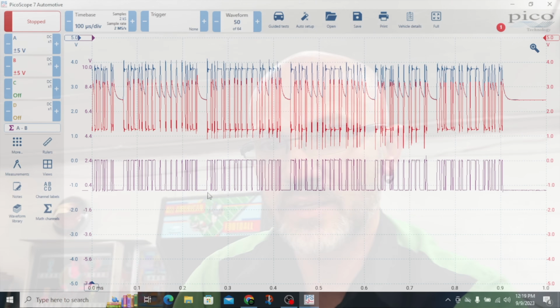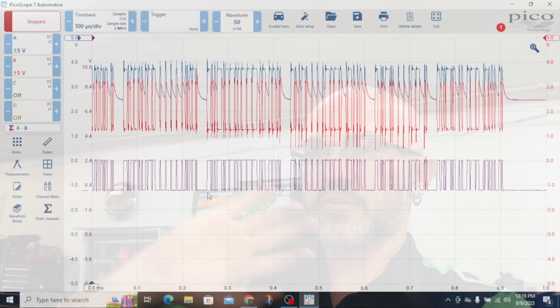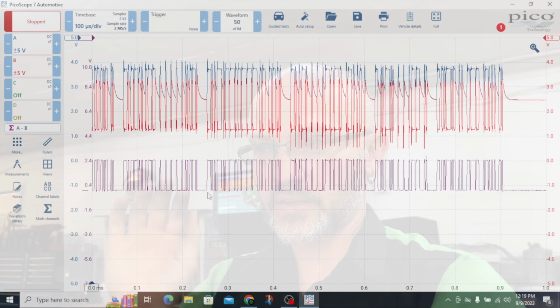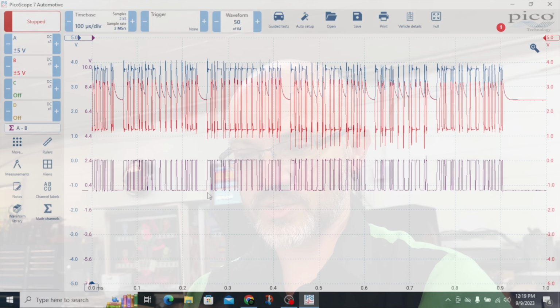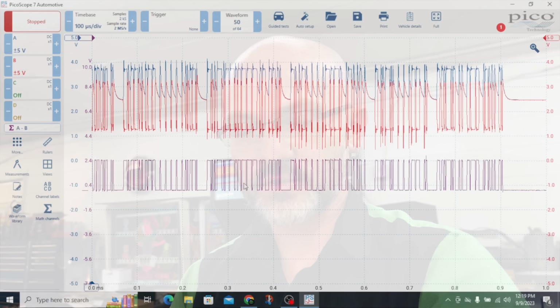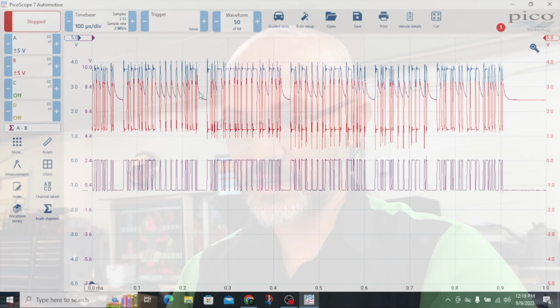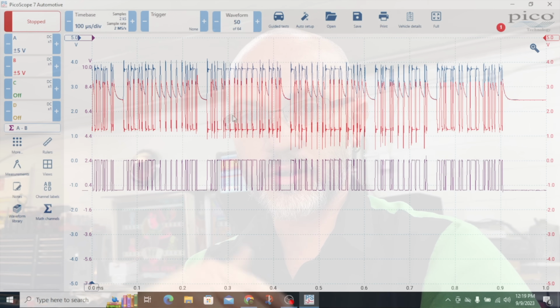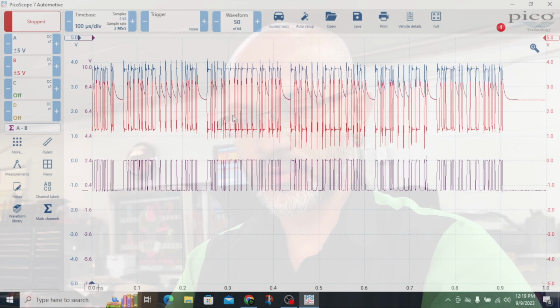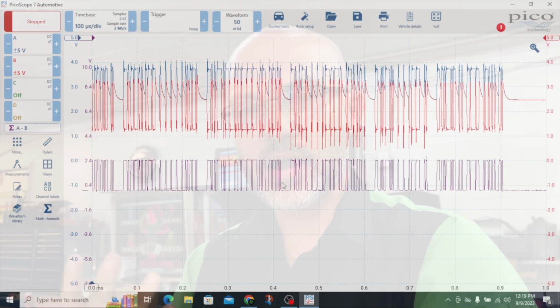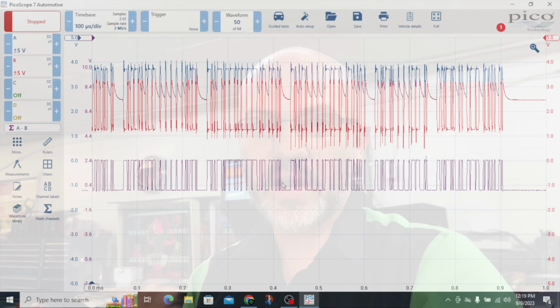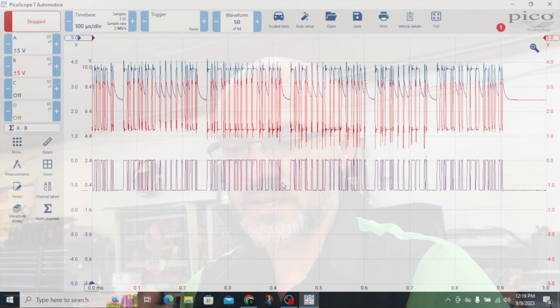So now think, if all the other modules are fine, they can talk, it's because this is what they're seeing between each other. Their signal might look like this up here on that end of the network, but when you run the math channel, it's perfectly fine to them. They can communicate.